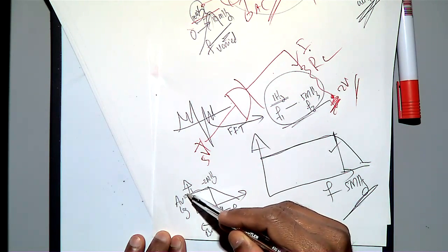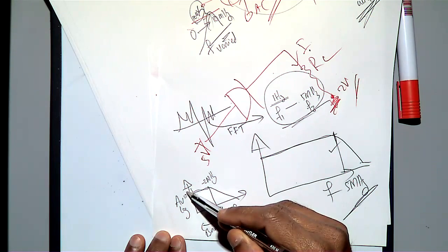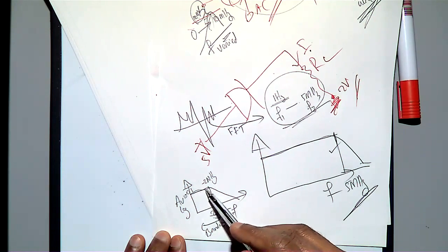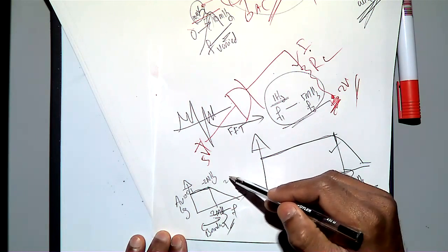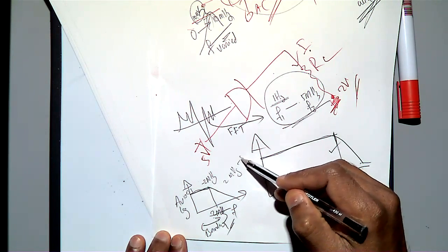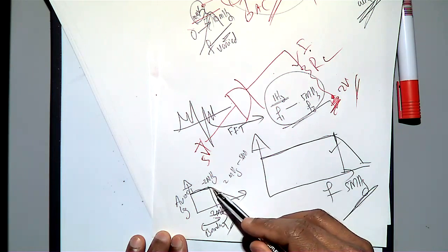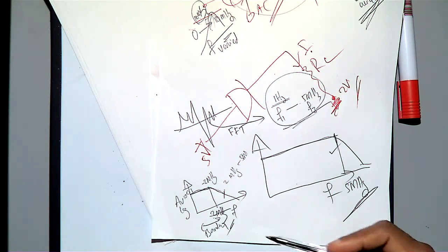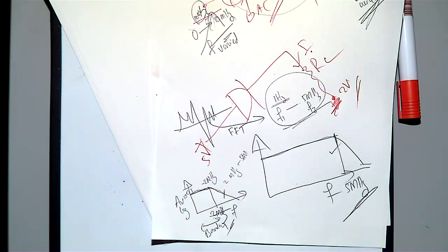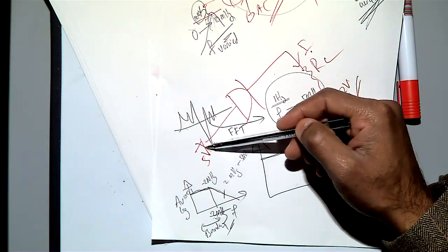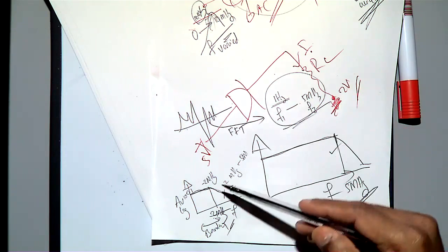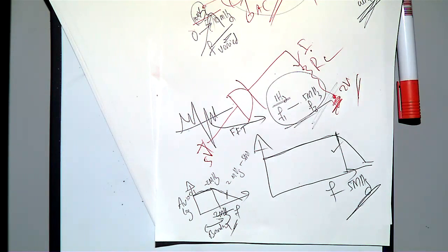Maybe this is equal to, say, 100. So in this range you get 100 amplification. For the remaining sinusoidal frequencies, 2 megahertz to 5 megahertz, your amplification is less than 100. So inside the signal there are so many sinusoidal components, and when you amplify, if you don't amplify uniformly, you will get distortion. So your signal will get distorted. That's the reason you should have the right bandwidth.